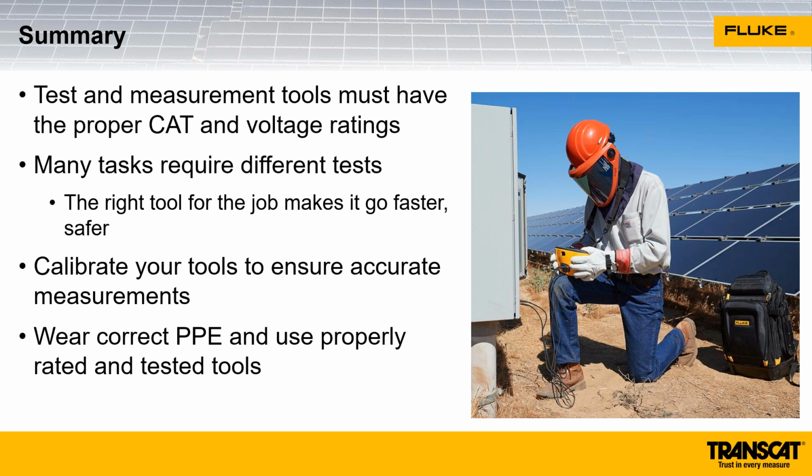So the type of personal protective equipment that you're going to need is going to vary based on the test that you're doing, the equipment that you're working on, the overcurrent protection devices in the circuits, and how close you are to the utility. It's all going to vary site by site, and even equipment by equipment.